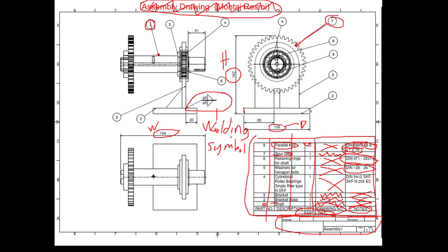of this assembly. And location dimensions, yes, this dimension is a location dimension, a coordinate. It says that relative to the right side surface of the chassis, this surface, the bracket is to be assembled 20 millimeters away. The location of the surface of the bracket is over there. It uses this coordinate 20. Okay. Well, another feature, 55, is a location dimension.